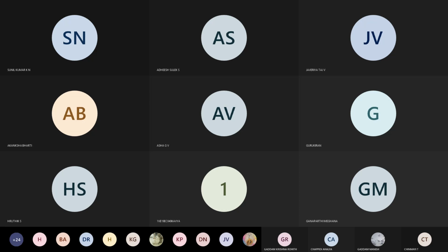If you simplify this, you will get VA by 3, VB by 3 and VC by 3. VA into R by 2 divided by R plus R by 2 is nothing but VA into R by 2 divided by 3R by 2. The 2 gets cancelled, R gets cancelled, so it is VA by 3. Similarly, when all three input voltages are given, the voltage across V1 will be equal to VA plus VB plus VC, divided by 3.